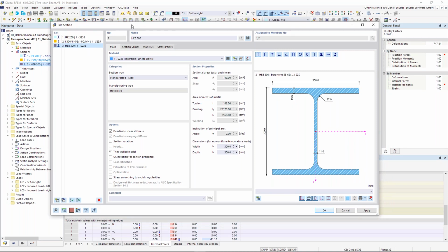And this can also be considered for your hand calculations. Because when you calculate by hand, with the help of some tables in your books, then it is kind of rigid. Then the books take no shear stiffness into account. Yeah, but in reality, there is a little bit of shear stiffness, especially when you have solid cross-sections or timber cross-sections. However, it is recommended to consider the shear stiffness for the deformation analysis.